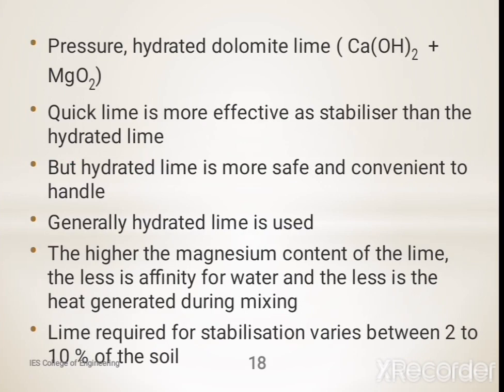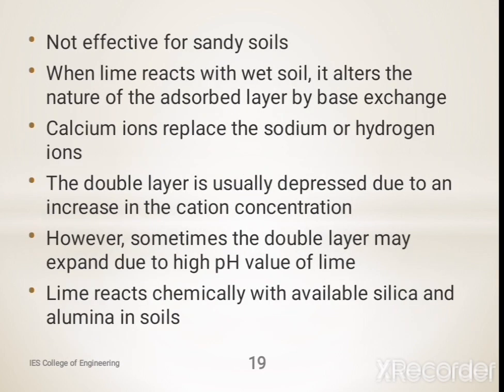Quicklime is more effective as a stabilizer than hydrated lime, but hydrated lime is safer and more convenient to handle. Generally, hydrated lime is used. This hydrated lime is also known as slaked lime. The higher the magnesium content of the lime, the less is its affinity for water and the less heat is generated during mixing. Lime required for stabilization varies from 2 to 10% of the soil. Lime stabilization is not effective for sandy soils.